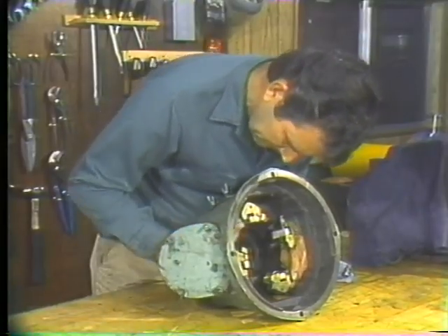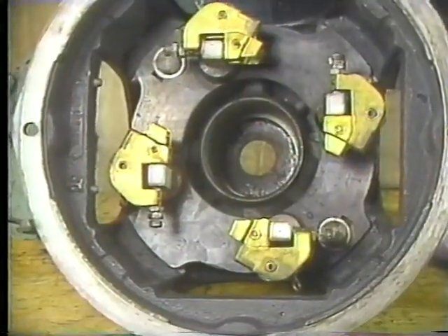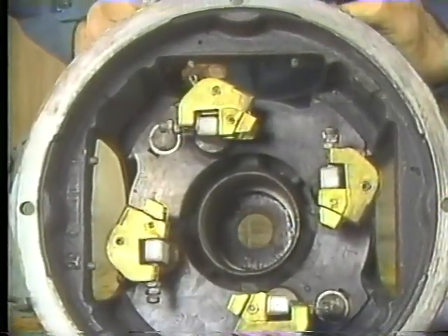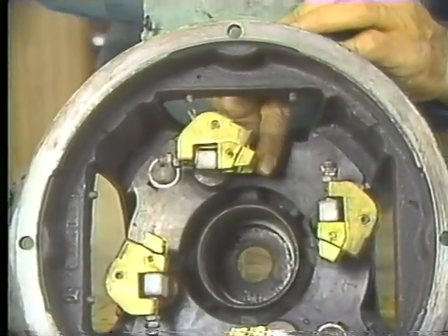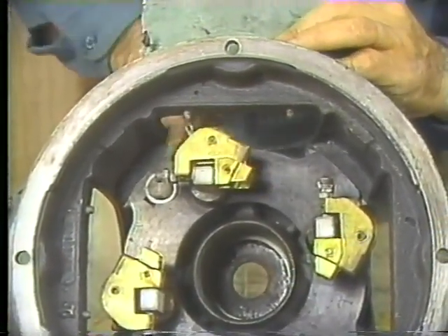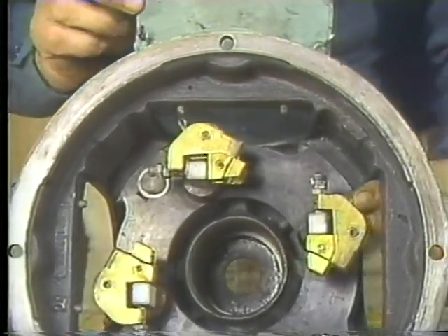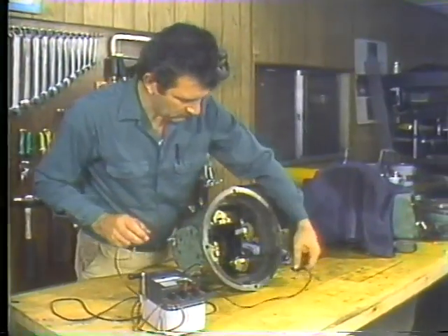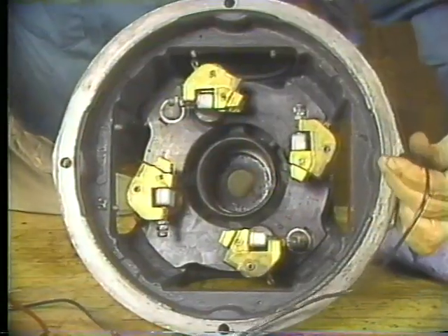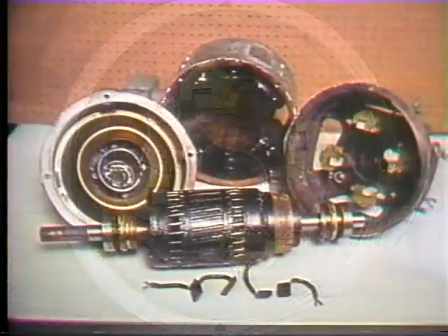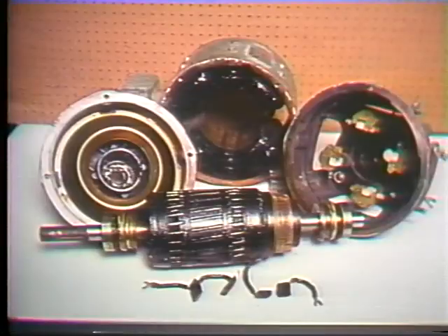We've already talked about inspecting the brush rigging at length, so I'll just mention the high points. Check the holder for bends and dings, the tensioning device for broken parts, and the pigtail connection screw. Then use the megometer to check the rigging for grounds. Okay, the last part is clean and inspected, and we're ready to reassemble.